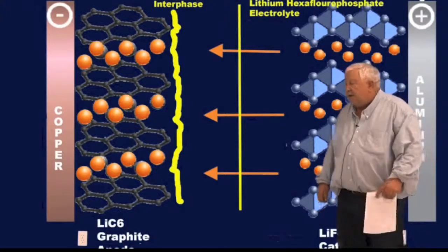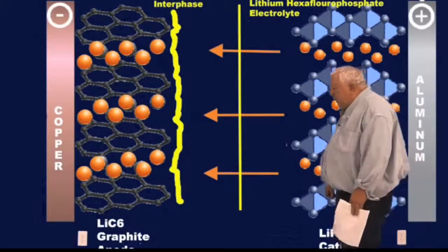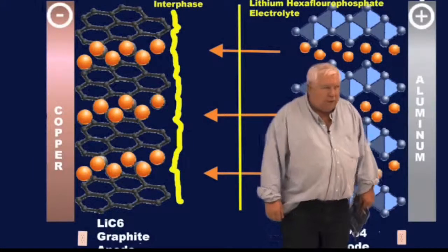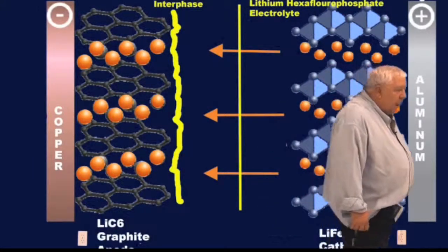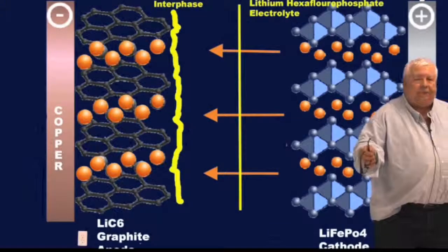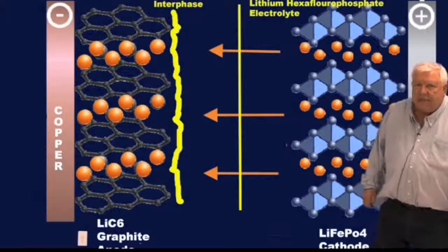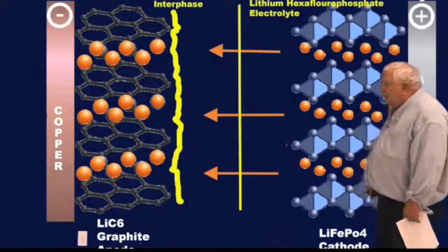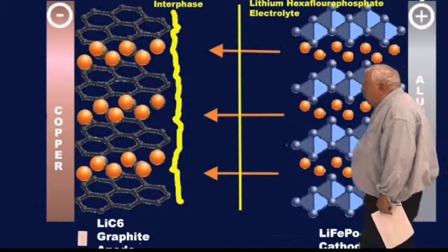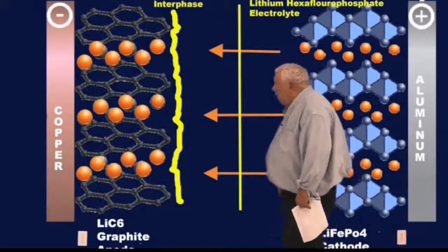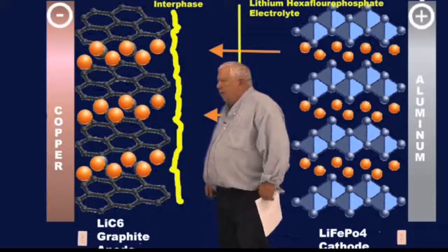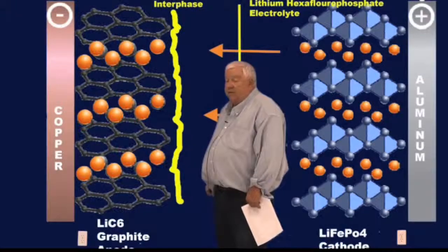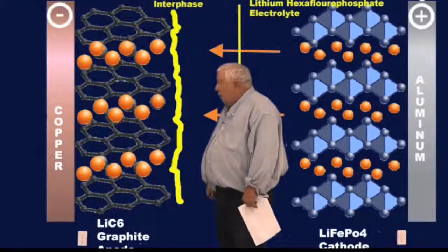We actually recently had our first experience of an over-discharge causing a fire, and it was with an A123 battery that we over-discharged and then let sit for 6 days. And on the 6th day, it burst into flames, burnt 1.5 inches through a 2-inch maple tabletop, filled our shop with smoke, and was really quite a thermal event. And so be aware that it is now dead certain that over-discharge can also cause a thermal event.